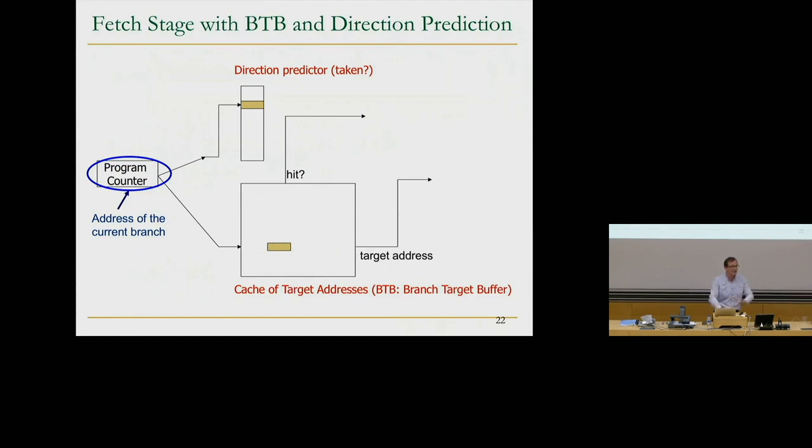We're not going to talk about how we design the structure yet. We'll talk about it when we get to the caches. But assume a structure: if you recorded a target address associated with a PC, the next time you ask for the target address for that PC, you get the target address and it gives you a hit. If you never recorded a target address associated with a program counter, you don't get it.